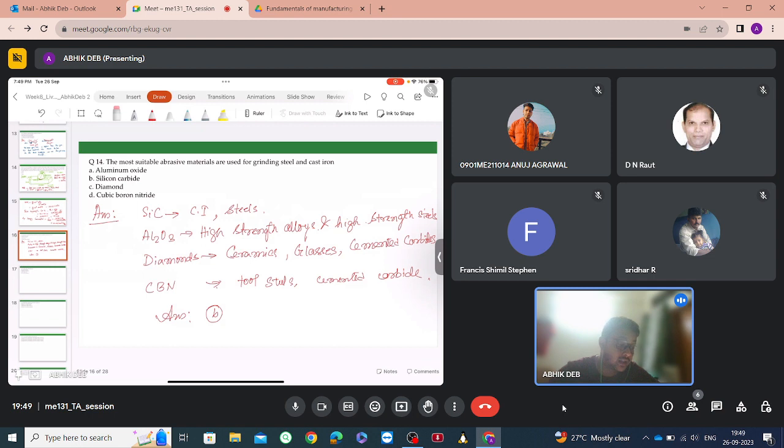That depends on what cutting conditions you are using, but in general diamonds have much higher tool life. But if you use diamonds with tool steels, or some ferrous alloys such as steels, there is a chance that the diamond will start to get degraded, because the iron in such ferrous alloys has an affinity for the carbon of the diamond, so it will diffuse into the tool region, and that is why it will start to wear out.